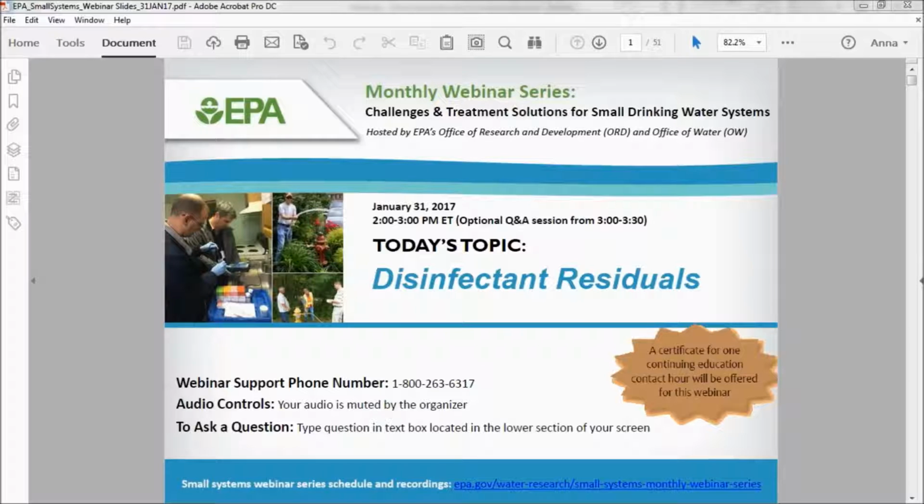Yeah. Okay, good. Here's a question related to the one I asked you previously about the bubble bias, and you mentioned temperature also. When you're at a system that has high or low temperature, or perhaps bubbles, how would you try to control that bias? With the bubbles, we'd recommend inverting the sample cell or tapping it to make the dissolved gas or bubbles go away, and visually confirming that it's not there. If there's condensation, also wipe the cell. But it's always good to check that before you read it in your instrument.